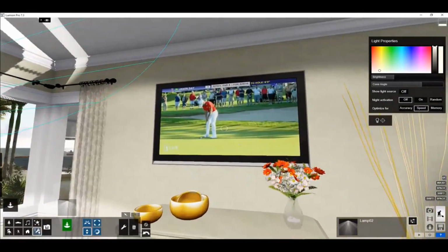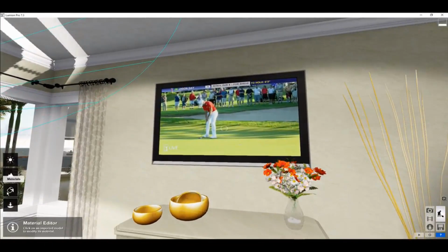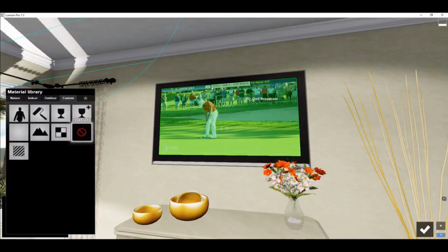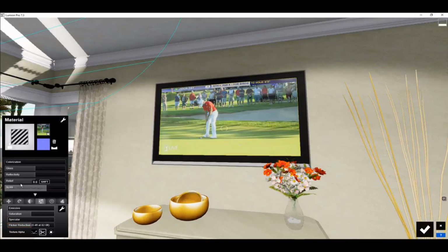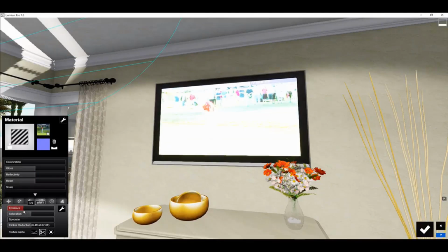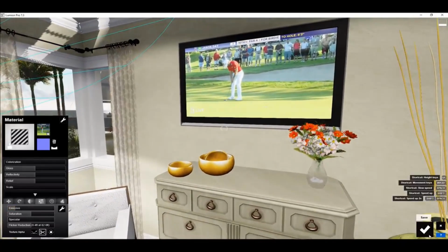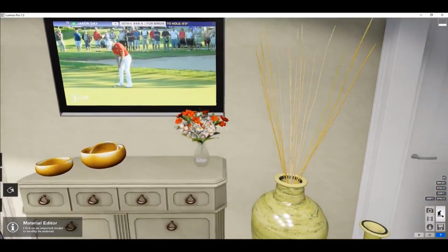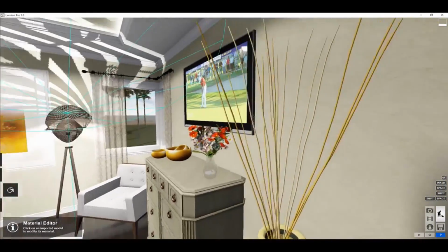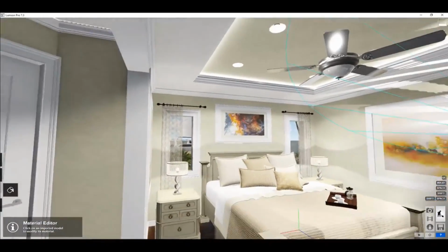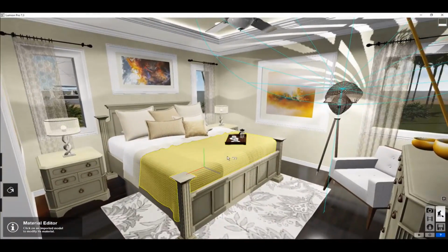Oh, one other comment about emissive materials. I almost forgot. This TV, it's killer. You can just go ahead and say this image is going to be a standard material. I'll leave its gloss and reflectivity, but let's just dial up its emissiveness to 0.1. If I just say 0.1, it makes that TV glow a little bit and gives it the feeling that it's on. That helps a lot for selling the realism. So looks like we're in pretty good shape.